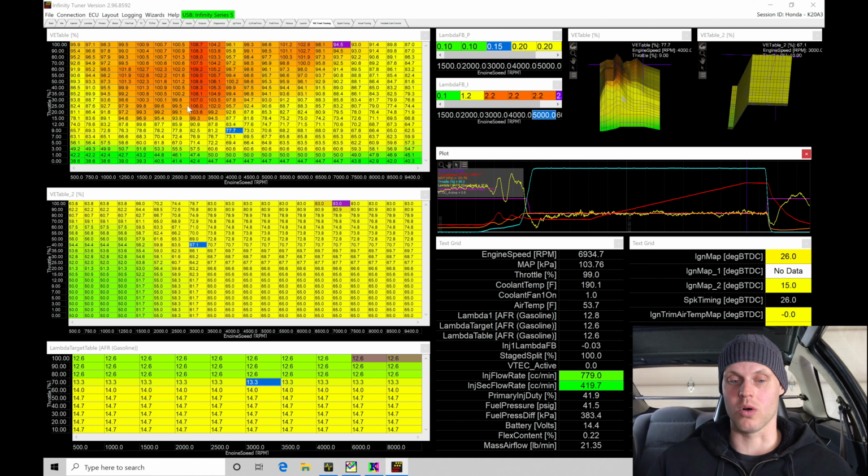These values are a little bit higher than what I would normally expect from a K-Series engine. However, this is highly efficient, so it's going to be demanding higher VE values because we have higher cylinder filling going on above and beyond what we would find on a typical K-Series engine. So this allows us to do a checksum, getting a feel for whether we've programmed our VE values in our table properly or not. In this case, we have. It's lining up almost within 5 horsepower of what it's showing on the actual dyno graph, so I'm confident in my VE values. That's just one thing I wanted to point out that I didn't mention in the last video.